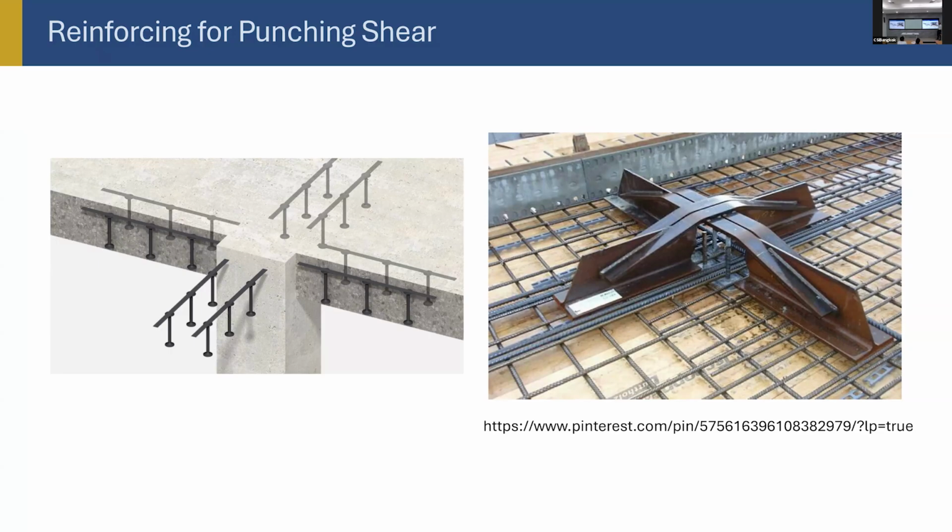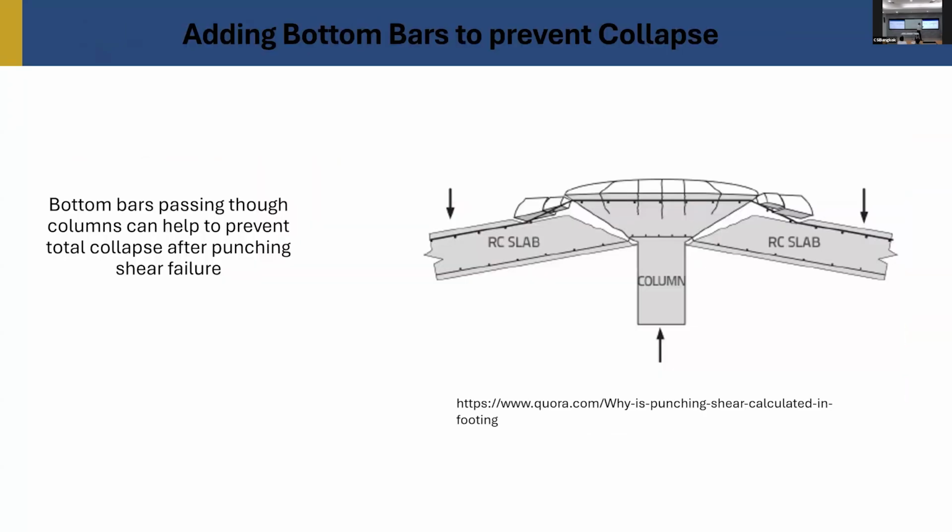On top of that, there's another prevention through a steel frame inside. Okay. So shear studs like that, or steel plate studs plus bottom bars, because people just don't want this to happen anymore. It is so serious. Of course, it's very serious. So that's the thing. You need to prevent this; the top bars do not help. So bottom bars are designed to carry the hanging slab now.